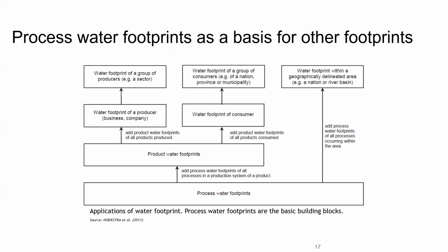Now again, two things are there. You are going to calculate two scenarios. One is the proposed scenario and another is the expansion scenario in case of environment clearance, right? In case of proposed, that means the industry is not running now. If the industry is not running, you can calculate the water on the basis of understanding from the mass balance. If the industry is already running, that is the second scenario, expansion. In expansion, we have to calculate exact data.